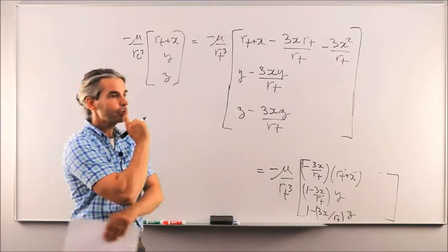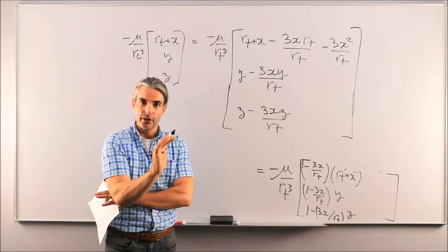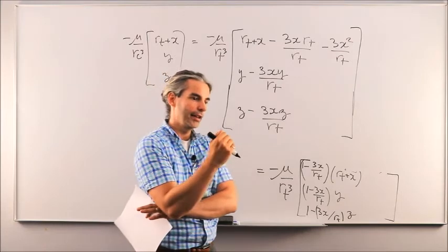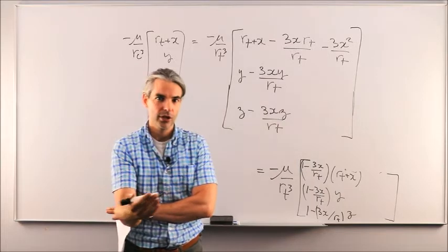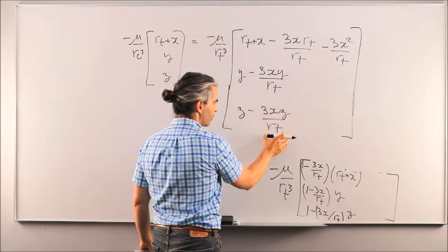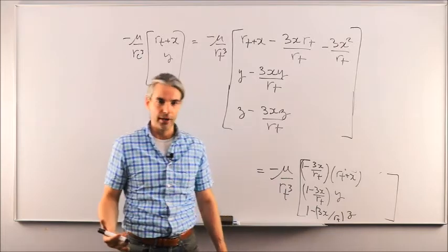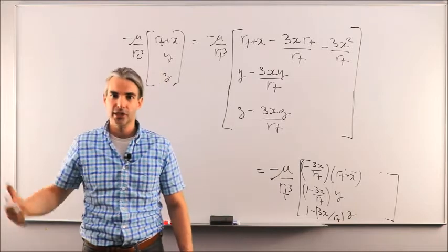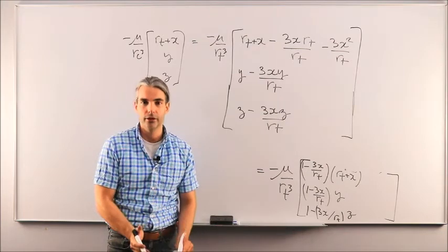So we said, okay, what we're going to do is to then linearize those nonlinear equations of motion, and the process to obtain a linear set of differential equations is to make some assumptions. The first one of which was to assume that X, Y, Z components were small compared to RT magnitude. And by doing so, I said that we're going to end up somewhere else with new equations of motion that would still be nonlinear. So we're going to make assumptions like that one after the other until the nonlinear equations of motion become linear at the end of the day.